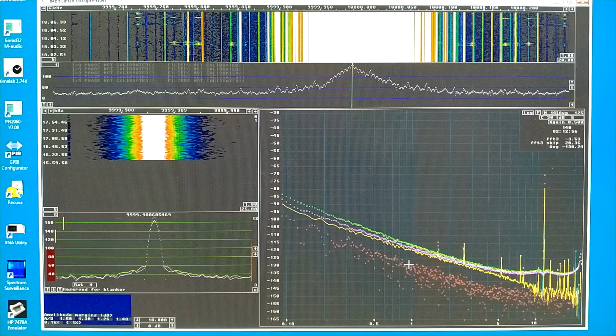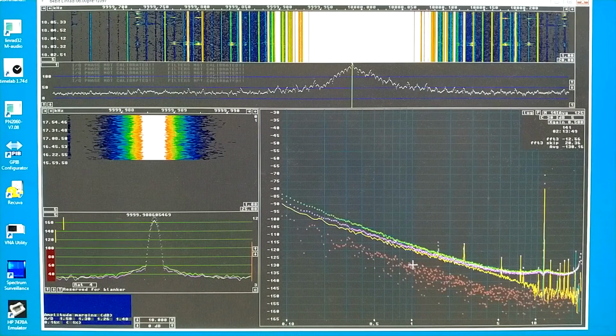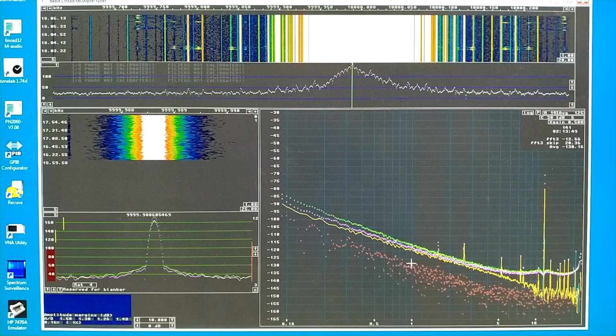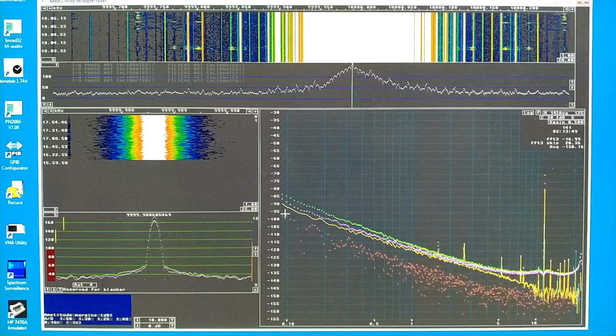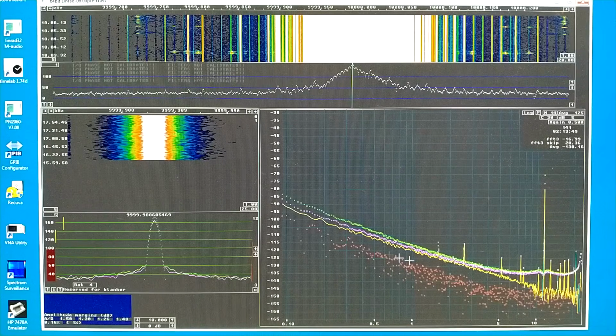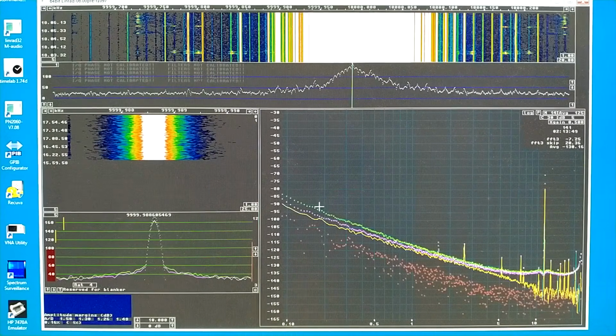The noise floor, as indicated by the imaginary part at 1 Hertz offset, is at about minus 128 dBc per Hertz. And it's more difficult to see where it is at 0.1 Hertz, but it's well below the level of the Wenzel oscillator, which is minus 93. So this looks more reasonable than before, but not much. The result at 0.1 Hertz is the big improvement.